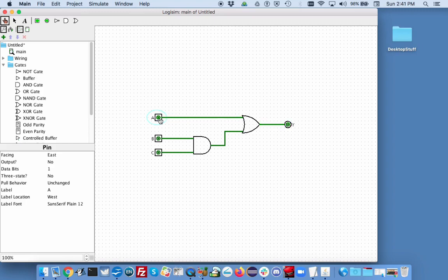When we poke the input, the value it has now appears in the input pin. This is difficult to read, however the wire connected to the pin will also change color. Dark green indicates 0, light green indicates 1. Now you can try the various input combinations and determine that our circuit functions correctly.